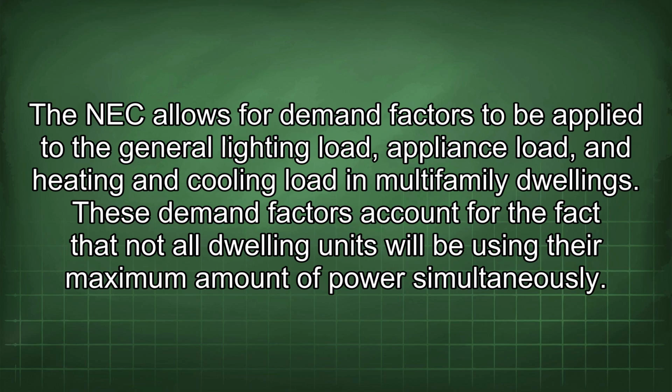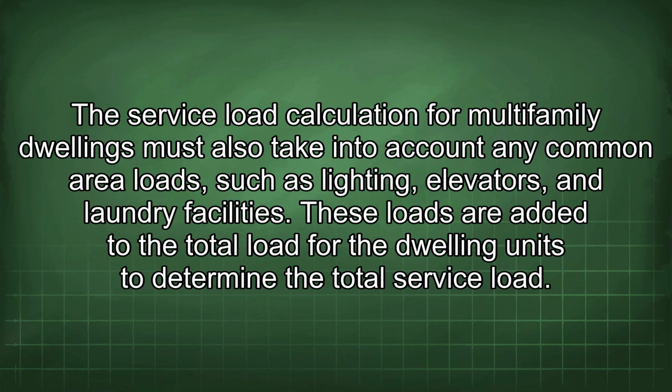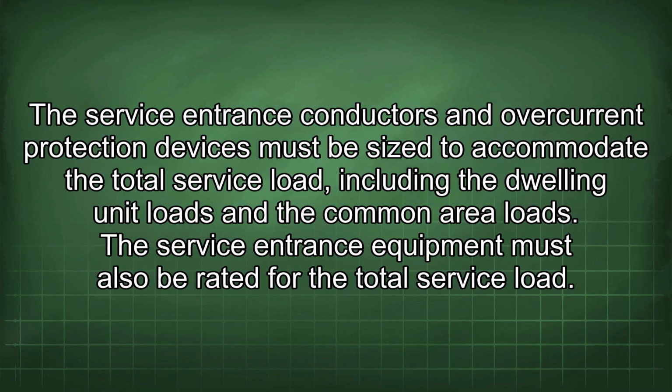These demand factors account for the fact that not all dwelling units will be using their maximum amount of power simultaneously. The service load calculation for multifamily dwellings must also take into account any common area loads such as lighting, elevators, and laundry facilities. These loads are added to the total load for the dwelling units to determine the total service load. The service entrance conductors and overcurrent protection devices must be sized to accommodate the total service load, including the dwelling unit loads and the common area loads. The service entrance equipment must also be rated for the total service load.